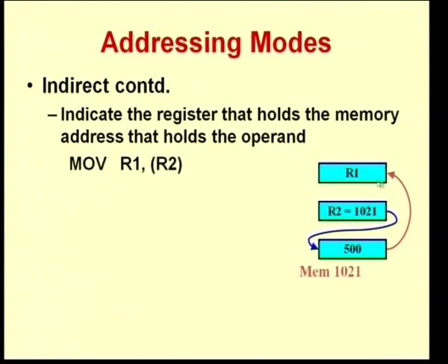It could be memory based indirect addressing or register based indirect addressing; both modes are normally used. The more common method in many instruction sets is register based indirect addressing mode. Now, there is another variation of indirect addressing, called auto increment addressing mode or auto decrement addressing mode. Here we do pretty much what we do in an indirect addressing mode, but we also do something more extra than that.